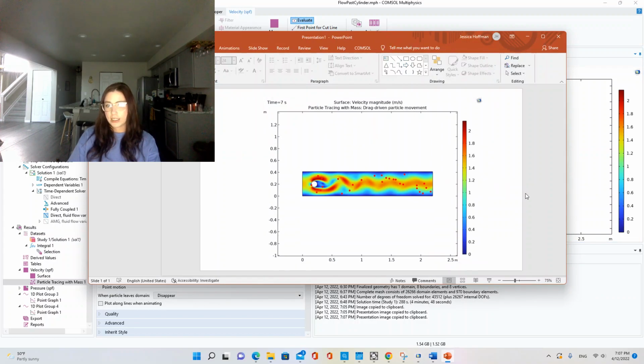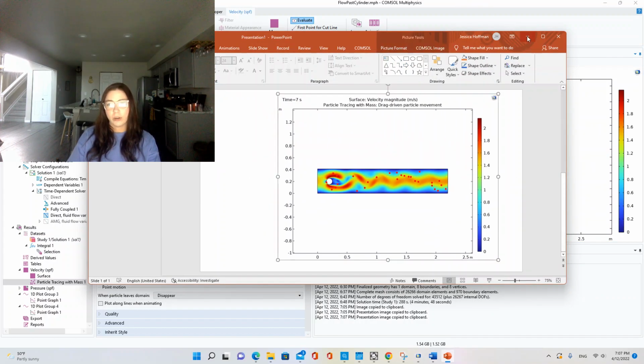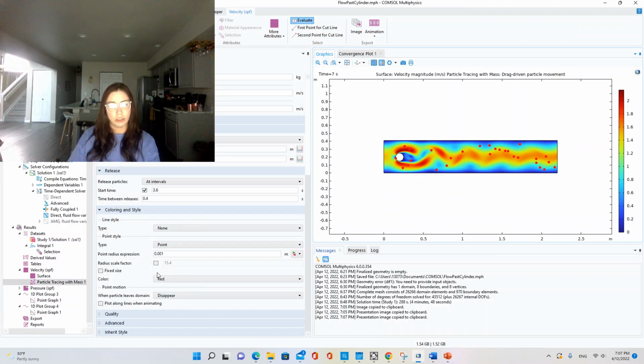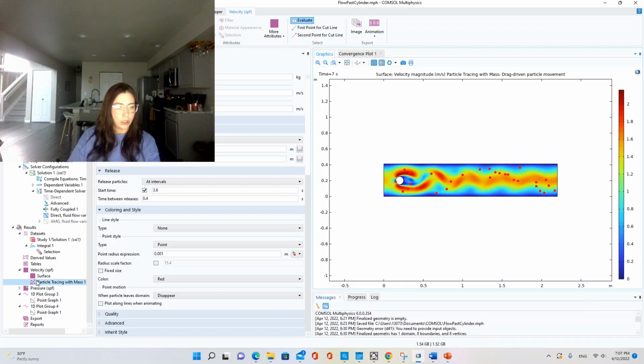All right, so what else? You can also do a simulation to show the time progression. So let's try to do that here. This was not in the tutorial, but if you click on the contour plot you want to animate, you can also do, let's see. Oh, under the Velocity SPF tab at the top, click Animation, Player.